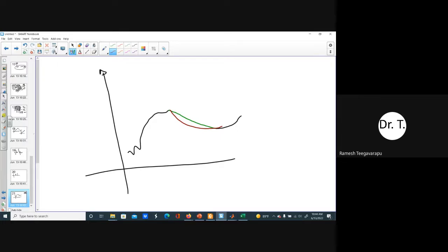Now, why do you think there is persistence in this data set? For example, the stream flow data set, it is because of the watershed response. When it rains, the watershed responds slowly, so the water moves towards the outlet, and then slowly we will see a hydrograph raising, and that slow raising of the hydrograph indicates that the persistence is very strong, and that really helps us in establishing the interpolation models.